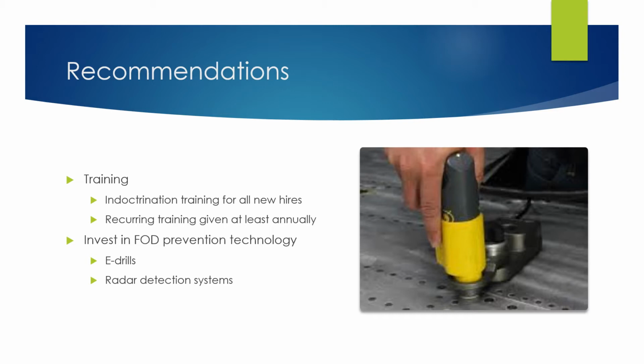From the research collected in this case study, I've come up with 2 recommendations. The first is training. A thorough FOD indoctrination course should be given to all new hires in a maintenance department, because while most technicians have completed an airframe and powerplant course or certification, it cannot be assumed that they are FOD experts. Additionally, recurring training shall be given at least annually to all employees to help emphasize the maintenance department's focus on FOD elimination and prevention.